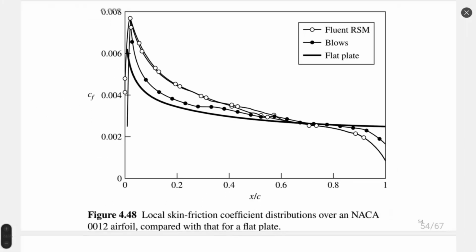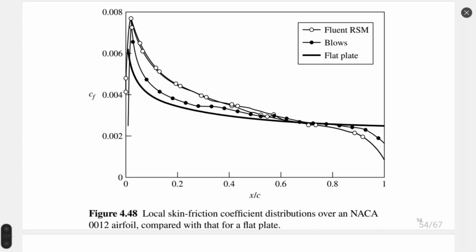Some data about skin friction. Skin friction coefficient on airfoil and the flat plate, you can see how close or how far these data are. For the flat plate, the thick black line is smaller, an underestimated friction coefficient.